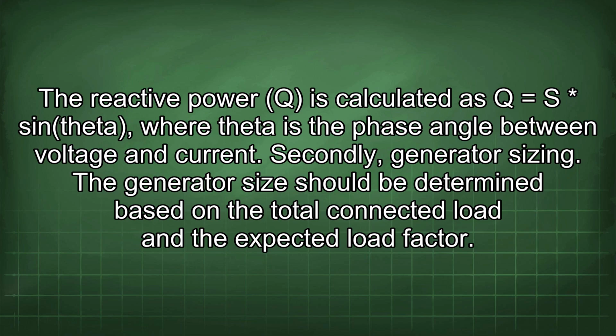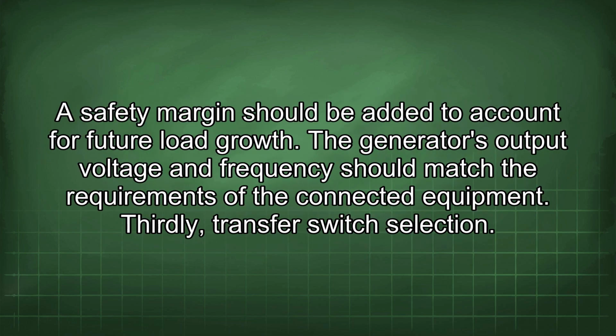Secondly, generator sizing. The generator size should be determined based on the total connected load and the expected load factor. A safety margin should be added to account for future load growth. The generator's output voltage and frequency should match the requirements of the connected equipment.